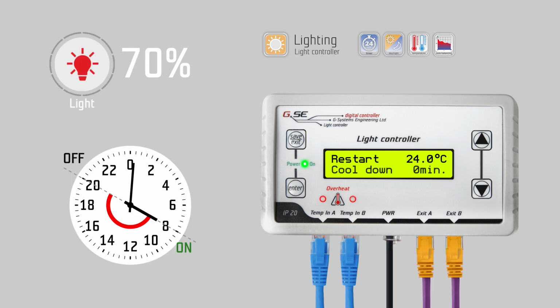The cool down time is made for high-pressure sodium, ceramic, or metal halide bulbs. This value starts the countdown when they switch off, and doesn't allow them to switch on before the time has elapsed. For LED lamps, put this value to 0.